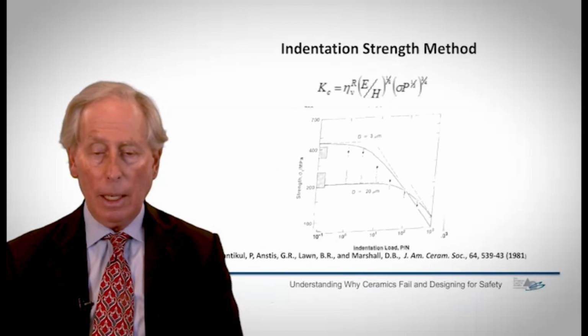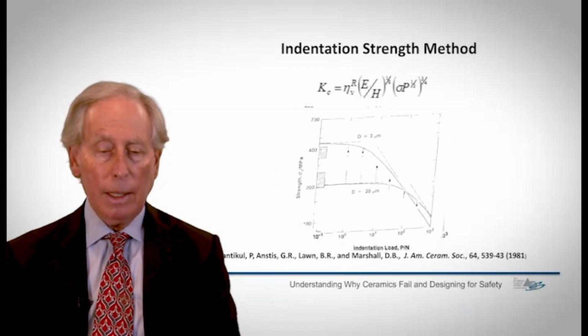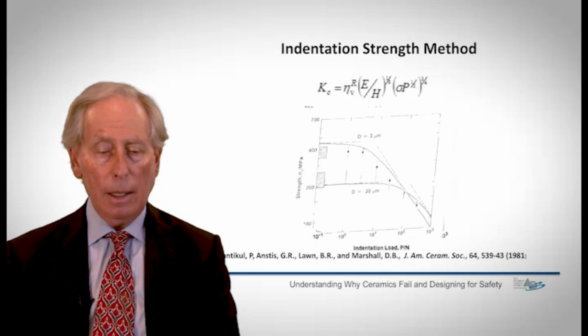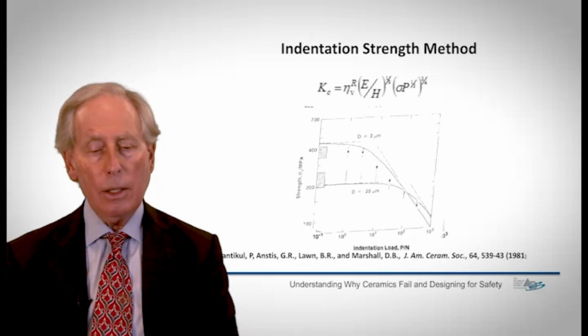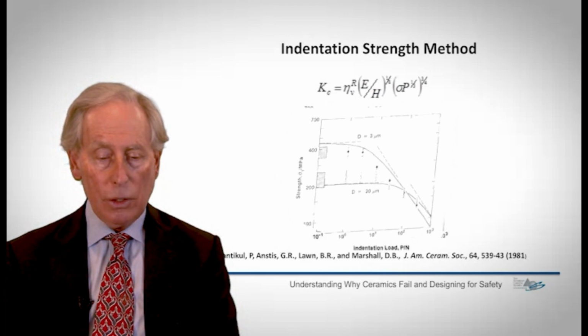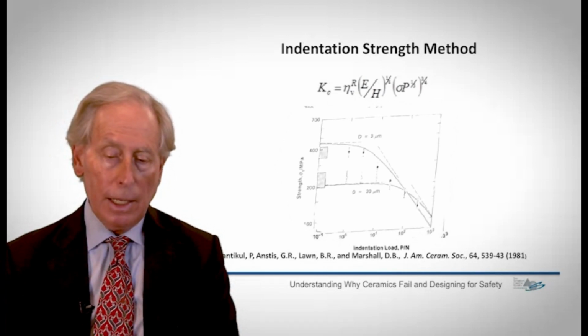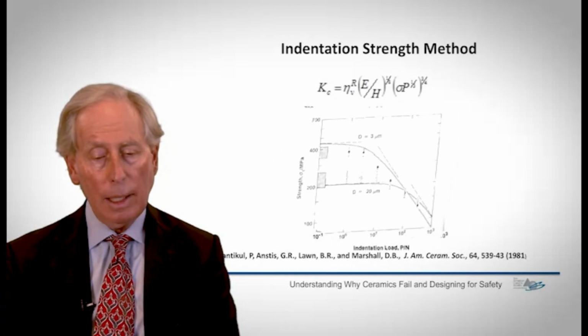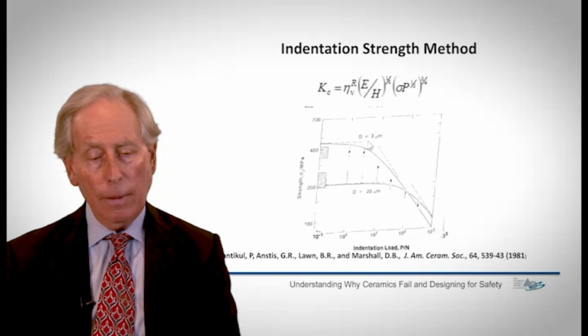There's another method I want to talk about briefly, which is called indentation strength rather than indentation crack length. And in this case, I put that same indentation into a bar of material and I measure the strength as a function of the indentation load in which I put the indentation, and I get a series of curves that look like this.